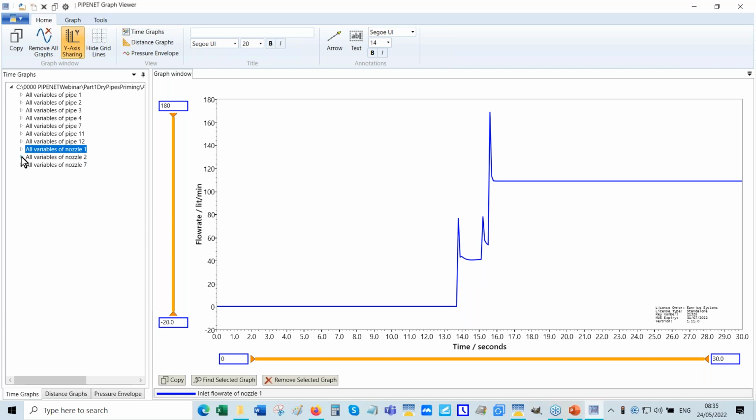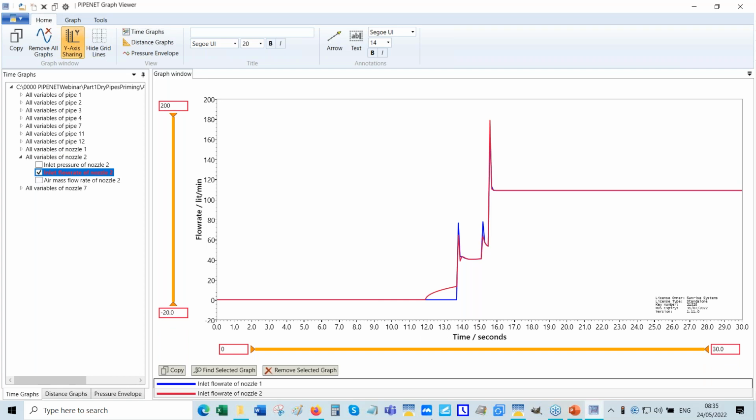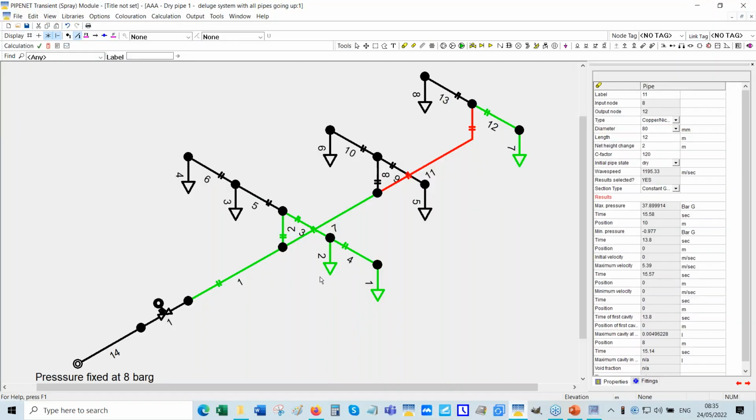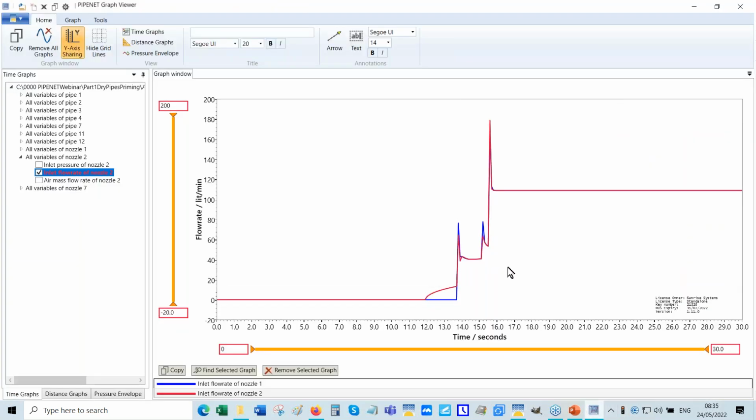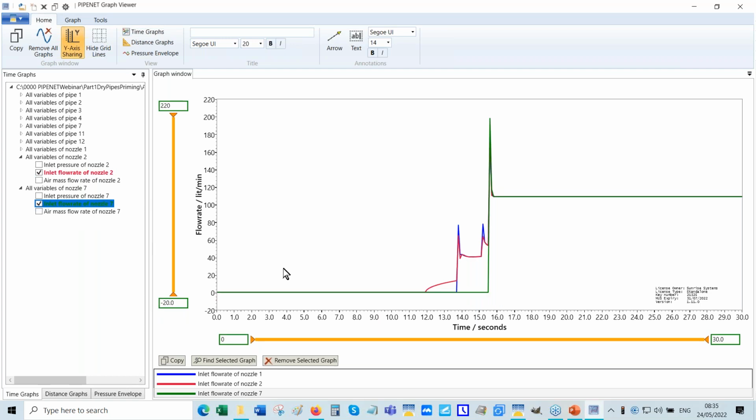And if you look at nozzle 2, that's nozzle 2, and that's nozzle 1. So the interesting thing is that they all experience these little spikes because of the shock wave that travels back to them. Okay, and let's look at the last nozzle. See, that doesn't have these little peaks because that is the last nozzle which creates a shock wave.